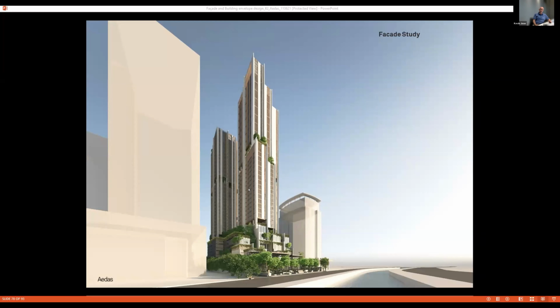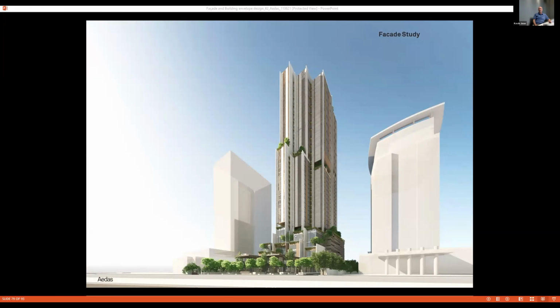And this is then from the form, we started looking at the typical facades. We started looking at bringing nature into the building, through the building, up and over the building. We really wanted to accentuate natural ventilation and greenery through the podium especially. And looking at the planes and breaking down the mass of the building, north and south facades having the main glazing, east and west, again, very limited glazing to respond to the solar gain issues of the rising and setting sun in Jakarta.